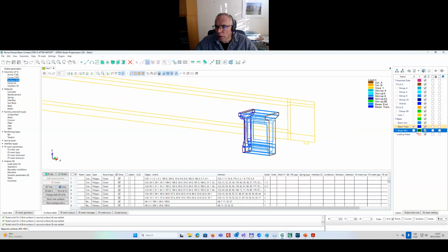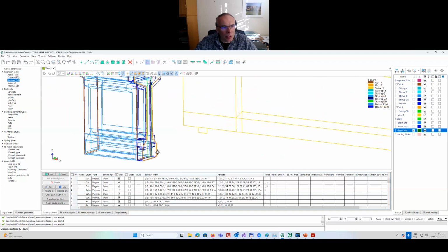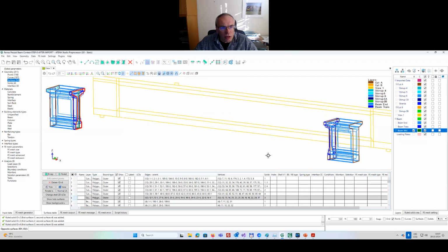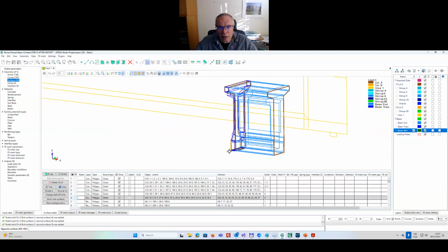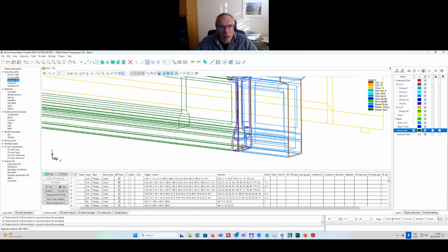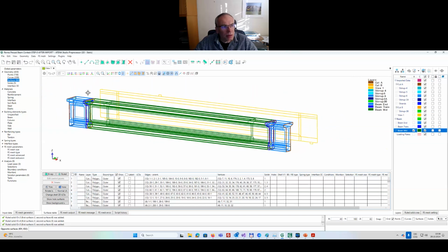Now I go to create the middle region. So I again activate the layer where I want this middle part to be present. It is always a good idea to divide my structure to various layers. That means I need to prepare these layers and then create the structure on these individual layers. So now you see we have completed the beam generation. So we have our beam.